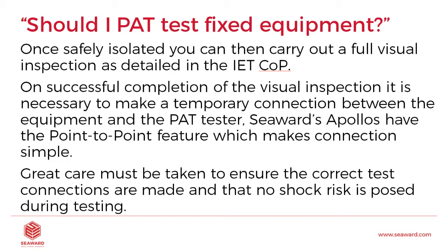Once safely isolated, you can then carry out a full visual inspection as detailed in the IET Code of Practice. So on successful completion of the visual inspection, it is necessary to make a temporary connection between the equipment and the pat tester. The range of Seaward Apollo testers have the point-to-point feature, which makes connections nice and simple. Removes the risk of having to use or invest in installation testers. The facility is built in within the pat tester. And of course, great care must be taken to ensure the correct test connections are made and that no shock risk is posed during any testing.